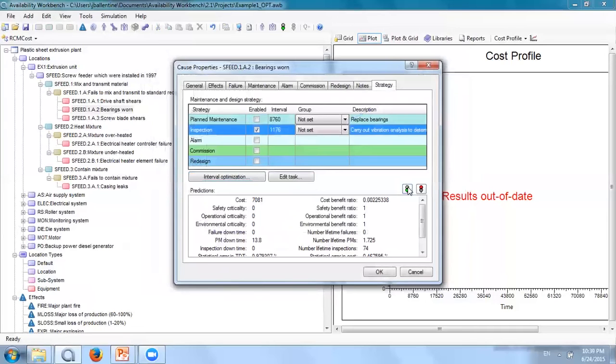I started at 3.1 million. I'm now at 7,000. And the reason I'm at 7,000 is I'm doing condition-based maintenance. I'm replacing the components when they need to be replaced. I'm able to order the components in time to have them delivered to site to actually be done. It's done planned, so I don't have to call people in, don't have to pay any overtime for it. It's a much better way to do my maintenance. And maybe we all know this is the right thing to do, but here I'm actually quantifying it. I'm giving justification behind what I'm trying to drive my maintenance program to be, which is this condition-based maintenance program.